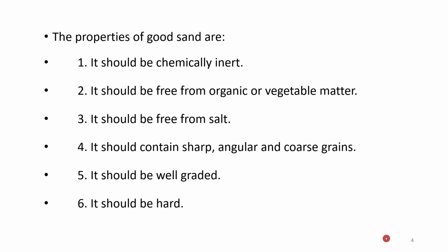It should be free from salt. It should have some sharp and angular structure to make effective bonding. Should be well graded. That means there should be a range of sizes so that it will best fit volume-wise. Should be hard.